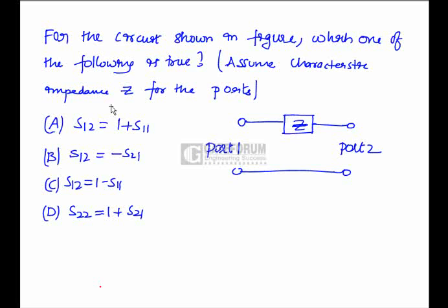Look at this question now. It doesn't give any information about which parameters these are. It has directly represented it as S. We have different two-port network parameters: Z, Y, transmission parameters T, T dash, and H parameters and G parameters. It does not give any information regarding which parameter you have to find. It is directly represented with S instead of Z, Y, T, T dash, H and G. People think that S represents short circuit or Siemens.